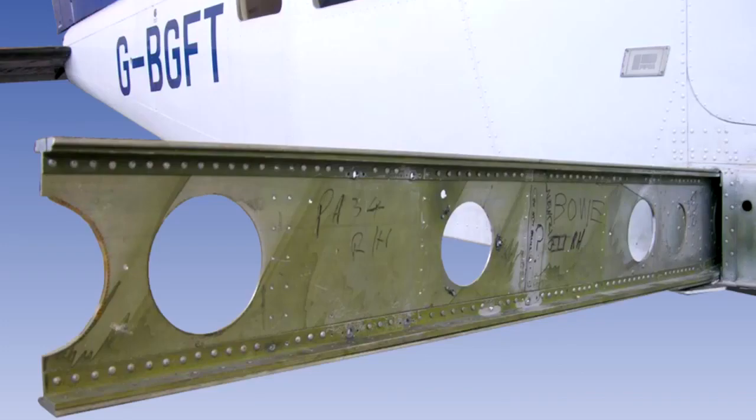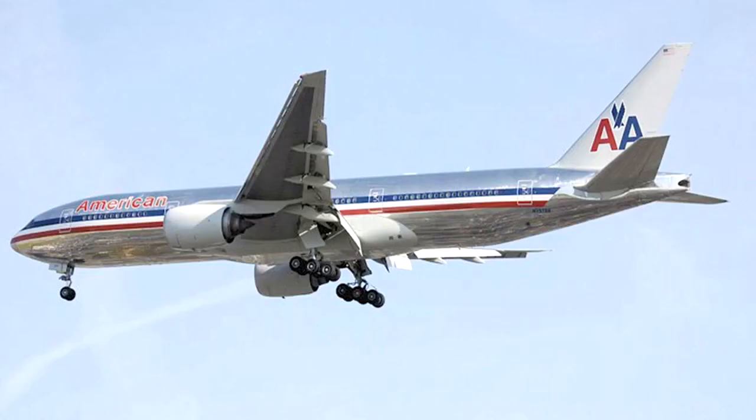Aluminium alloys are the most widely used metals for structural use due to them having a good strength to weight ratio. Duralumin is an aluminium and copper-based alloy which has poor corrosion resistance except when clad with pure aluminium. It has good thermal and electrical conductivity and good fatigue resistance, but it is difficult to weld. Aluminium-clad duralumin is the most popular material in use for airliner skins.